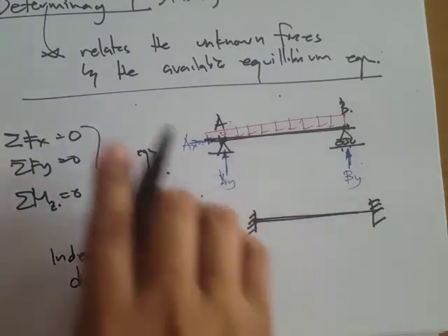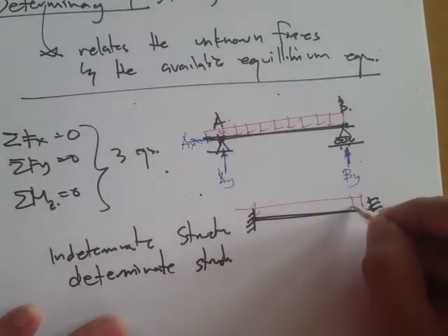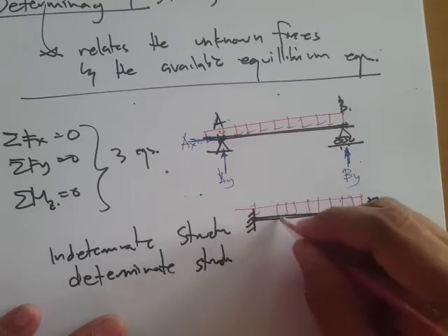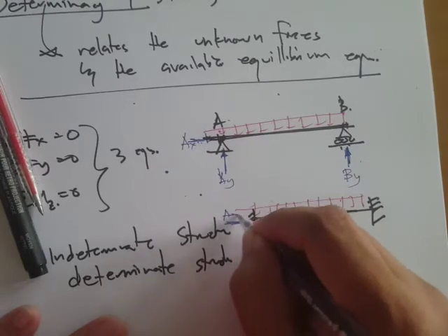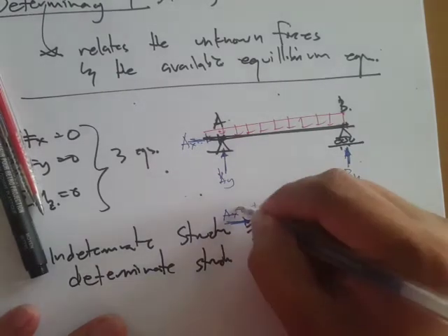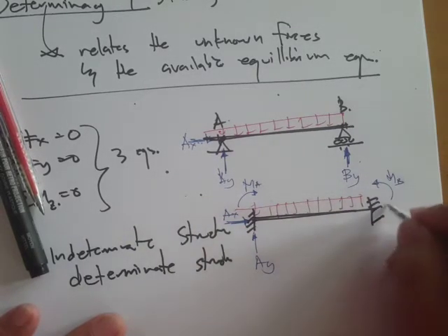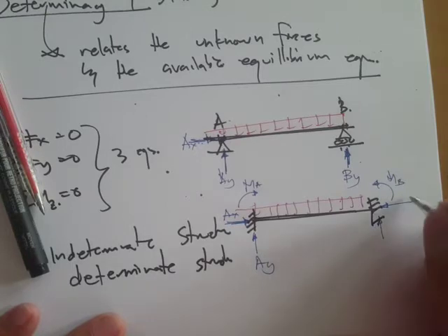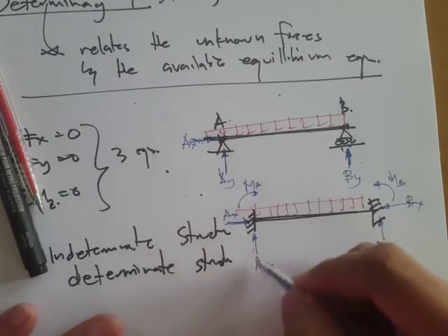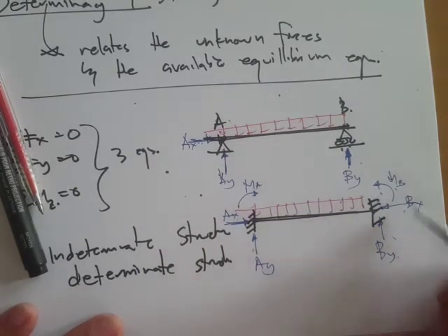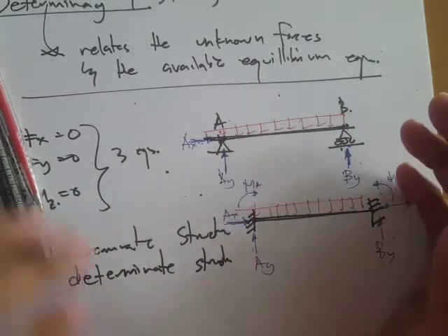Okay, that's a fixed beam, and let's say under external loadings, recall that we have, say, AX, AY, and a moment. Say so moment here, the same thing, moment along B, X, and BX and BY. Okay, so how many support reactions do we have? We have three. Three on this side, three on the other side. So six all in all.